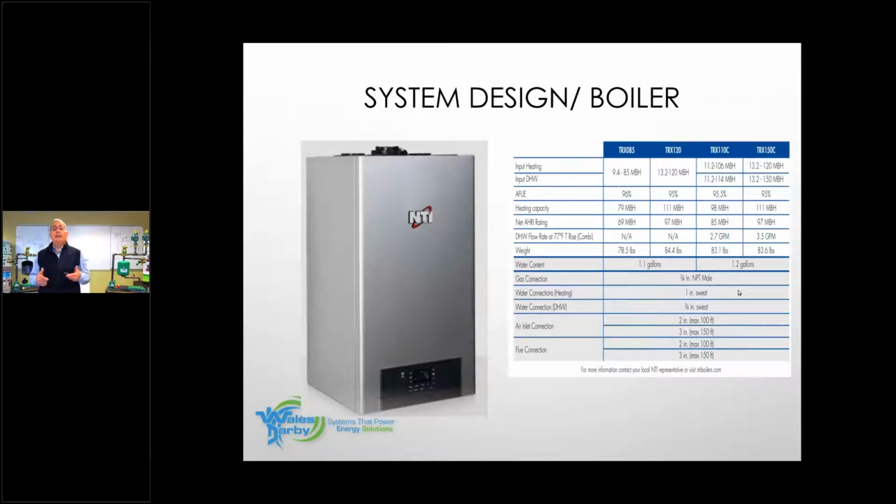Now, if I go and put the boiler in conditioned space, now that basement is heated, or say it is up on the first floor, since this boiler is going to pull outdoor air for combustion, and then we're going to vent out from the side, I could put this, say, on the first floor in a closet, and now I'm within conditioned space. So that means now I don't lose that 15% from jacket loss or piping loss. That's very important for you to know, because that gives you an advantage when you are picking your boiler. Okay, especially when you're looking at cast iron. That can mean changing from one boiler size to another based on where that boiler is going to be located. All right, so for today, our heat loss for the whole project was 52,000 and change.